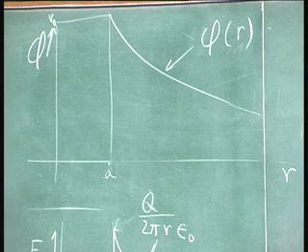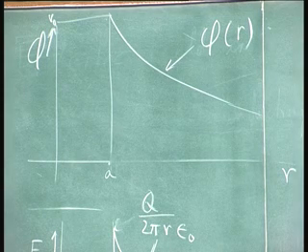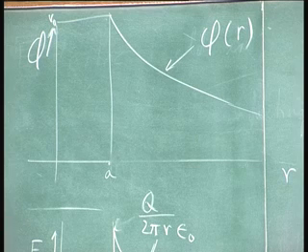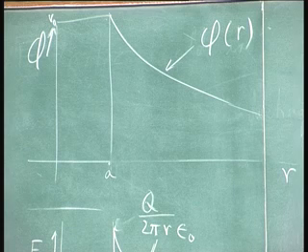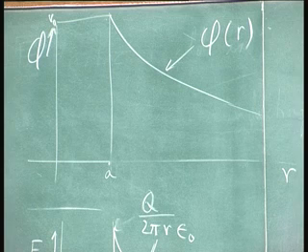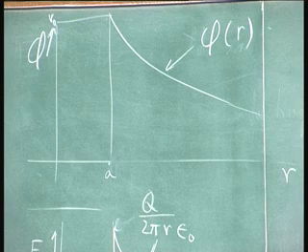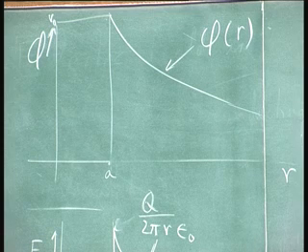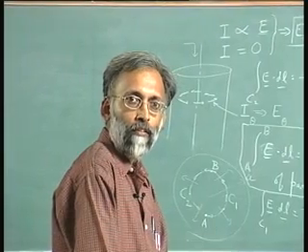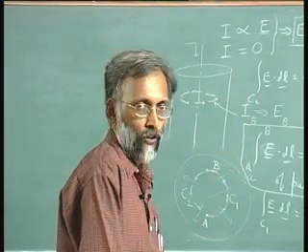These are important results. They are important because the potential and field between two coaxial cylinders is a very common problem in electrical engineering. It is so common that there are very standard tabulated answers to these geometries. But here I am basically presenting this as a way of understanding how to solve problems using Gauss's law.